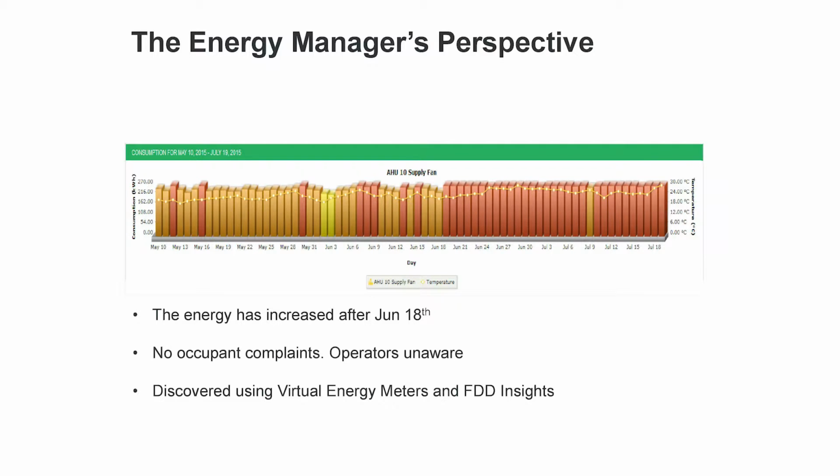So this is just an example of using virtual metering. In this case, we have the supply fan energy use, a virtual meter created for the supply fan in an air handling unit.